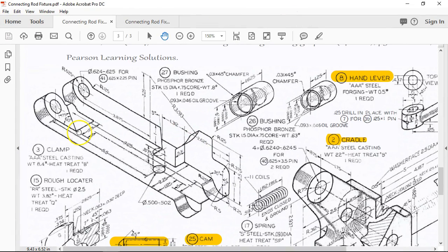Okay, the item 3 clamp then. The geometry is not overly complicated, a couple of cutouts. We'll probably end up referring back to the center lines early as well, but from the center lines over back, we're going to try to identify the overalls. So this kind of lends itself to contours and regions. I don't know that I need to do a layout sketch, given its complexity, but we can do some contour and region and maybe share some sketches to get this geometry in place.